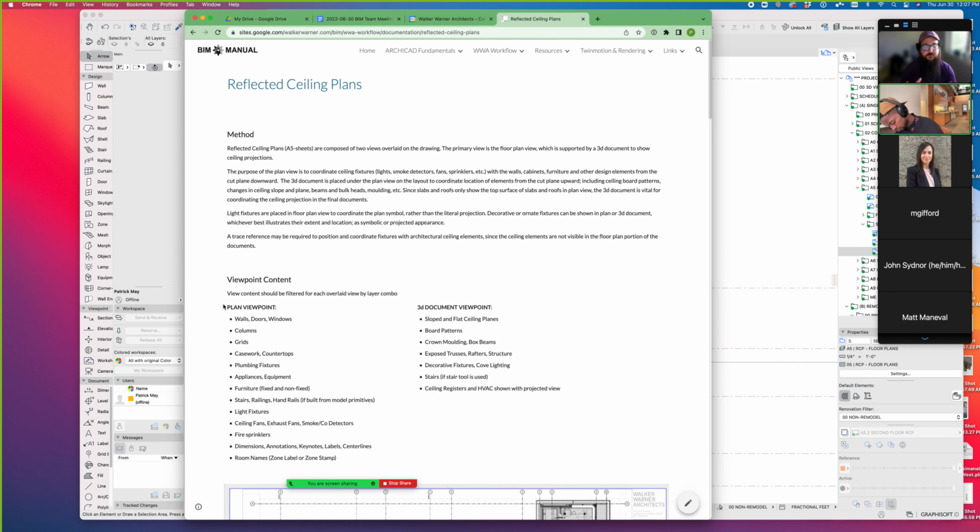So the light fixtures show in floor plan so that we can get the plan symbol appearance of those fixtures. Say a recessed can light shows up with its recessed can symbol in plan. In the 3D document, it would show the literal projection. So if you had something like a directional arrow associated with that can fixture, you don't get that in the 3D document unless you place the can in the 3D document directly, which is a 2D only instance. So we're trying to eliminate that redundancy. Or there are even cases before where we just left the cans out of the model and didn't rely on them for our rendering and things like that. So this allows us to have an all-inclusive system where 3D matches 2D, matches our documents.